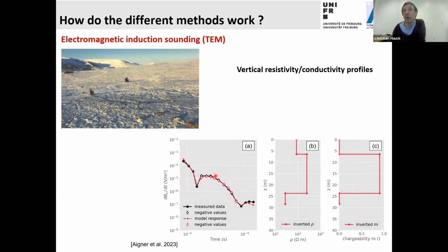In this case, a rock glacier, we see the base of the resistive zone here. So we see the base of the ice-rich part of the ground, which would be here 20 meters thick. So that is an alternative if we want to have a sounding. Again, we profit from the fact that ice has a very high electrical resistivity and the unfrozen part has a low electrical resistivity.